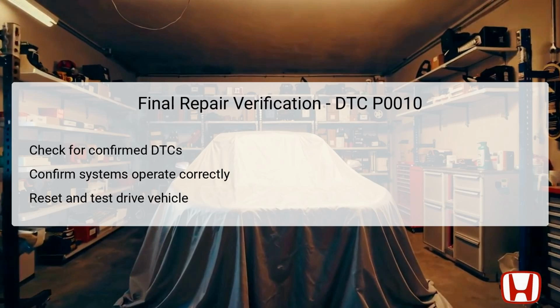After completing the troubleshooting steps and necessary repairs for DTC P0010, it is essential to perform a final verification to confirm that the problem has been resolved. Start this process by checking the Honda Diagnostic System HDS for any confirmed DTCs. If no DTCs appear, this indicates that the issue has been corrected.